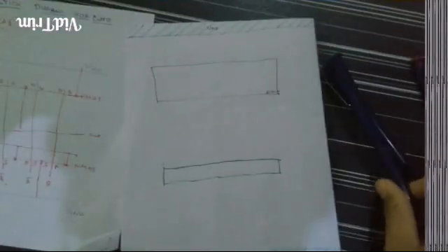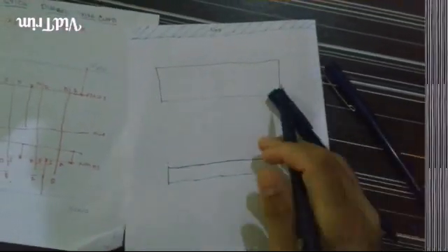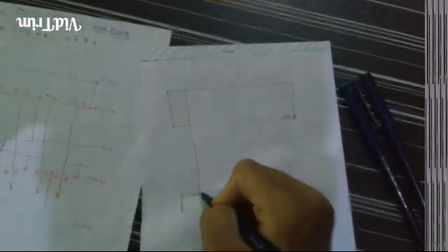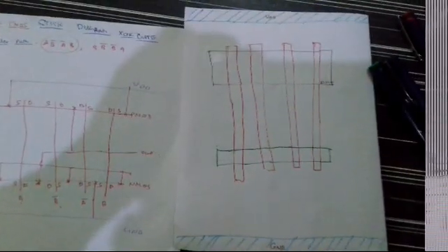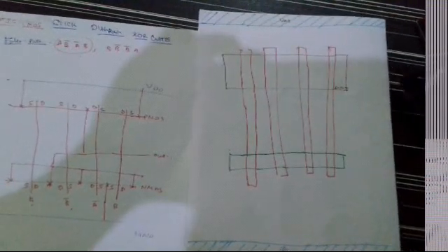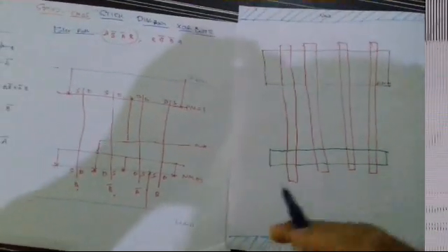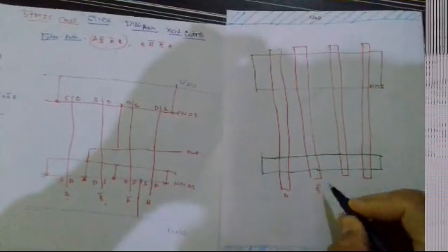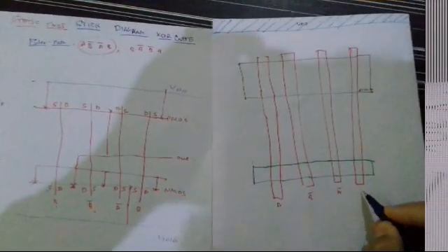Then next we have the polysilicon, which is made of red color. So we have 4 transistors, so we will space them equally. Now after marking 4 polysilicon layers, they can be named, as we can see in the stick diagram, A, B bar, A bar, and B.